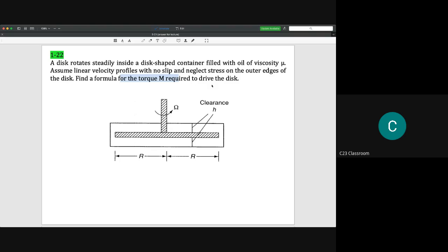So the first thing that you need to understand in this situation is which surface is moving and the form, the shape of the velocity distribution. For example, because we know that the disk here is rotating, then we could assume that we have a molecule here and also molecules stick at the top part, but the velocity distribution will be shaped like this.